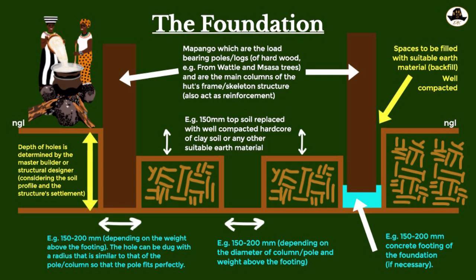It's a procedure normally done in construction, to replace the ground we are going to be stepping on inside the building with something well compacted and firm, so that we avoid the effect of weight which might collapse the foundation or make the surface uneven. When we put proper material that will be well compacted and firm, we won't have a sloppy surface on the floor. That's what we're trying to achieve as well.